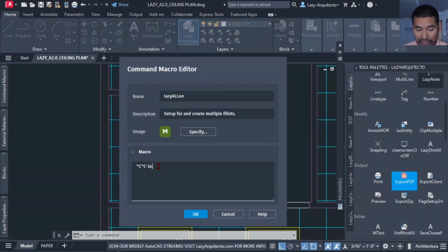Once I did that, I pressed enter, using this semicolon that represents an enter on your keyboard. Then what I needed was the thaw option. So that's why I used the T option to thaw my layers. And AutoCAD will ask me at this point, what layers do you want to bring on or thaw, right? The ones that I need, of course, were everything. So I used this character, the asterisk, that represents everything, and of course I pressed enter a couple of times.